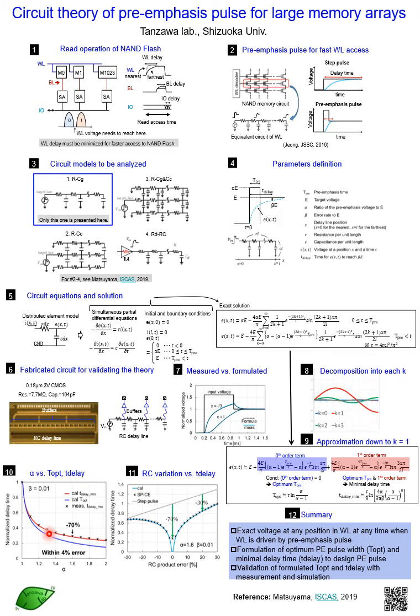Even though this value is not as much as the case with alpha of 1.6, from the viewpoint of the generator circuit, probably you would want a lower pulse height to simplify the design. So there must be a trade-off between the pulse height and delay time reduction.